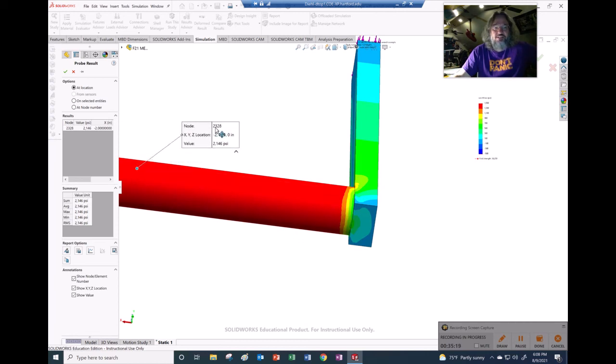This is just a single value that's supposed to represent all of those stresses. We condense the stress into one particular thing. We call it von Mises stress, and it's very useful to us. It's the default output in FEA because it's a nice single value that we can look at.